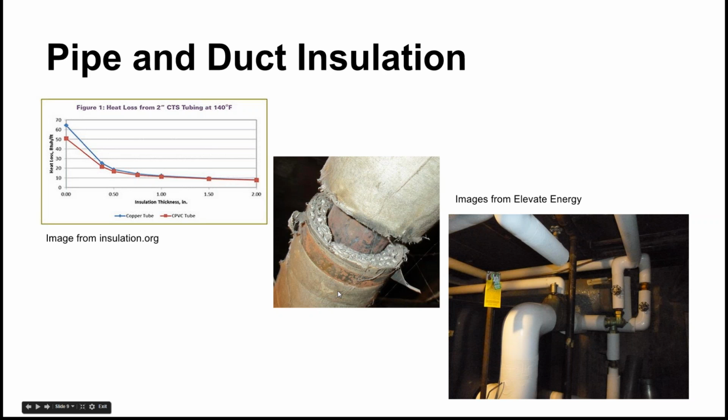So one caveat to this is that pipe insulation is a technology that's been around for a while. A lot of the older stuff has asbestos, and that's what you can see in this middle picture here. Any of this corrugated cardboard sort of looking old pipe insulation has asbestos in it, most likely. Asbestos is a really effective insulation material. It has a higher R value per inch than what we currently use, which is fiberglass, but as you all know, it's also a big health hazard. So if we see it, especially if it's cut open like this, we definitely recommend replacing it, putting in this nice looking wrapped fiberglass insulation instead.